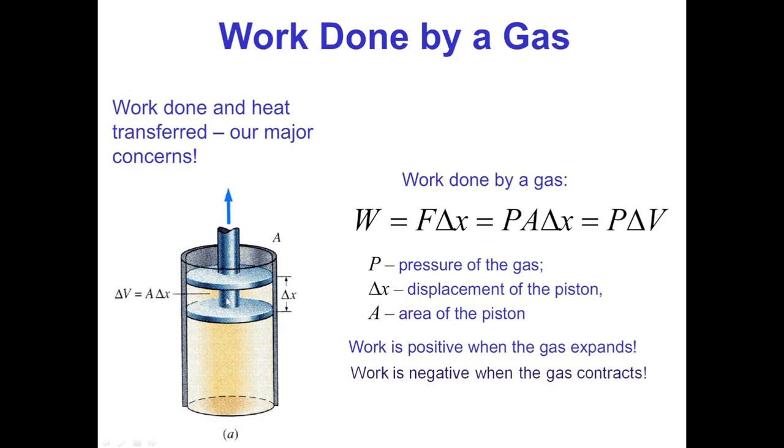The flat surface area of that circle is the only area inside the piston that's designed to move. So when the pressure pushes harder on that specific area, that creates force that pushes that circle and pushes the piston it's attached to further out. So the gas pressure times the area of the valve, the area of the circular flat part of the piston valve, is equal to the force that the gas is exerting on that particular flat circular part.